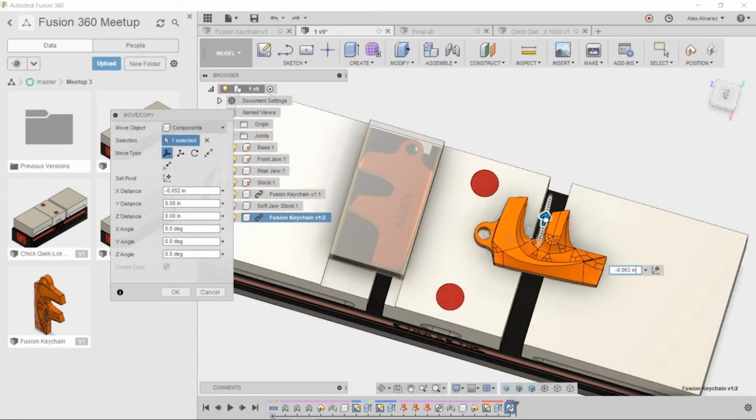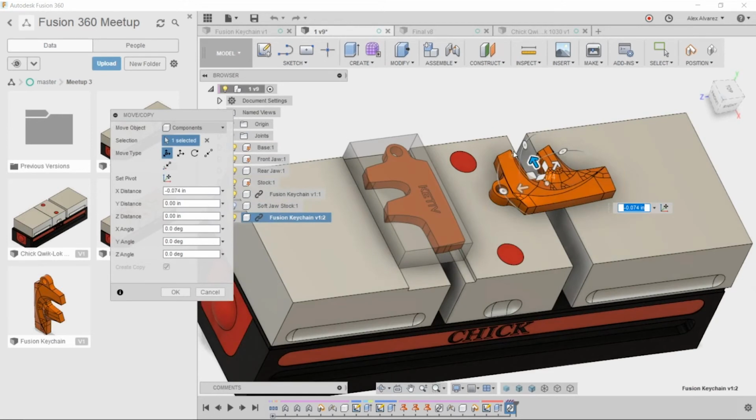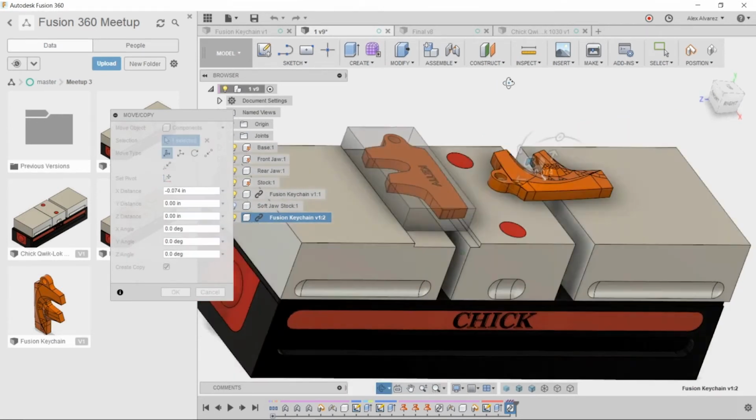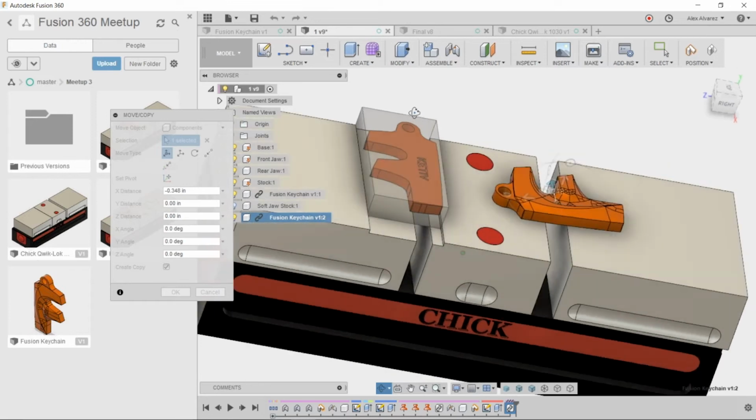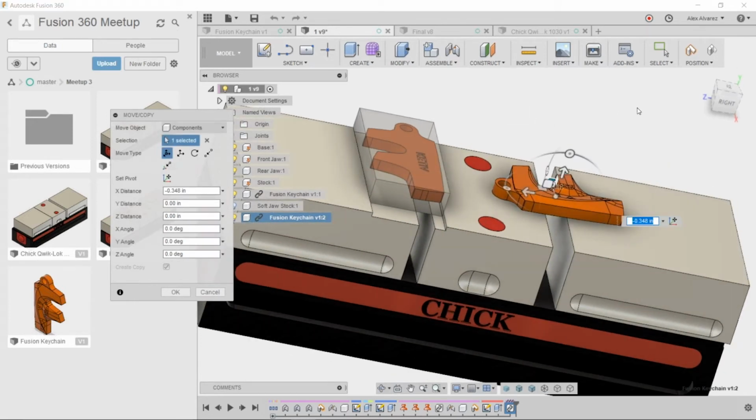Okay. Now, the neat thing about this is that, again, going back to the integrated CAD CAM, right? We're going to create our soft jaws and our part all within the same environment, right? So going back into the CAM workspace, what I can do then is have one single G54 or one single work coordinate. And now I don't have to worry about exactly where this part is going to be located, right? I don't have to be too worried about that when I'm machining it.